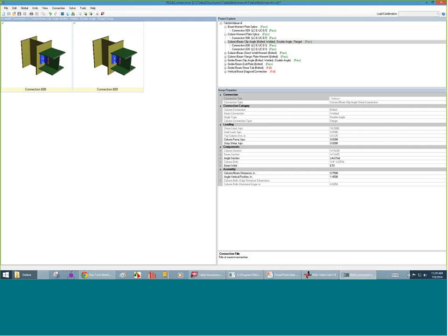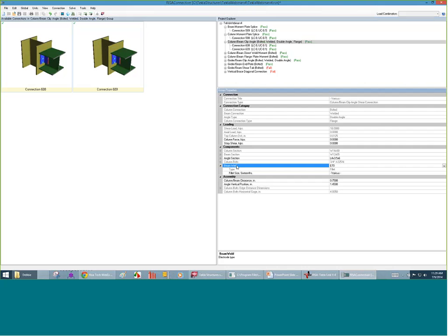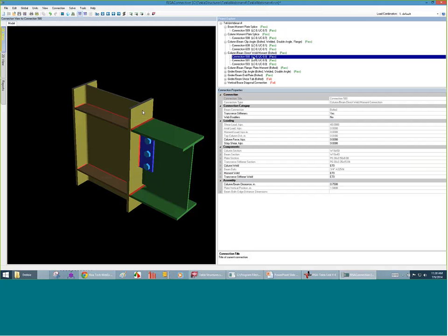And I can look on the right side and see that I want to change that beam weld again. It tells me that right now it has various sizes because I already changed one. So what I'll tell the program is I really just want to make them all 3/16. And it will then clear out the code check, and I can size that group and see if it passes. It's still very much under code check, but it just shows me how I can continue to size things down as needed.